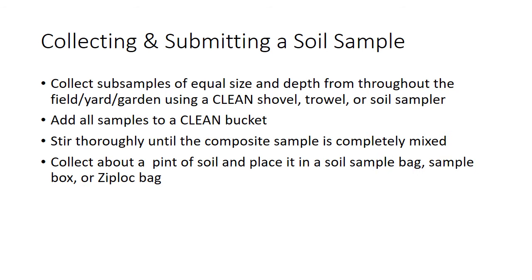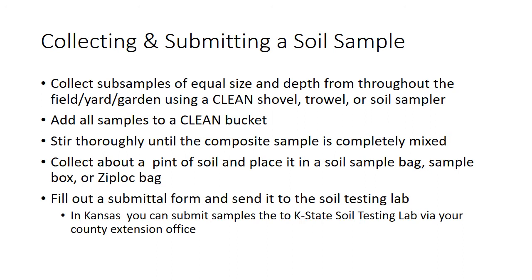And so we need about a pint of soil or a couple cups worth, and we can put that in a sample bag, or you can just use a Ziploc bag. And then when you submit it, there's a form that you fill out, and put your name, contact info, billing info, and so on. And also you check off the test that you actually want completed. You can submit these samples directly to the K-State Soil Testing Lab, which is in Throckmorton Hall, or you can do it through your local county extension office.